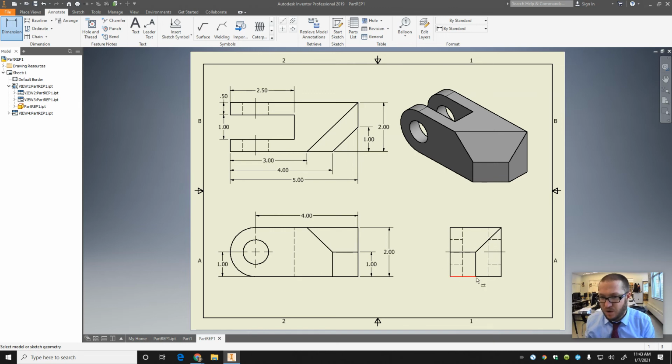So let's see, do I know this width? Yep, believe it or not, this 1 inch is this width here. This total width is 2 inches. The height, 2 inches, we know. This location, we know. Okay, we've got everything dimensioned. The only thing we don't have dimensioned are the diameters of this and this arc here. In fact, though, this will lead to an over dimension.